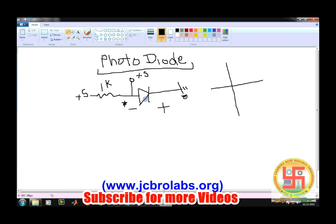But as light falls on it, depending on the intensity of light, it conducts. If it is conducting heavily, that means its resistance is decreasing, so the voltage across it will be less. If the light intensity falling on it is less, then the value at this point will be higher. So this V out value becomes a function of light intensity, that is, how much light is falling on it. If light intensity is increasing, V out will decrease. If light intensity is decreasing, V out will increase. This is the basic circuit diagram of the photodiode and how it is used.